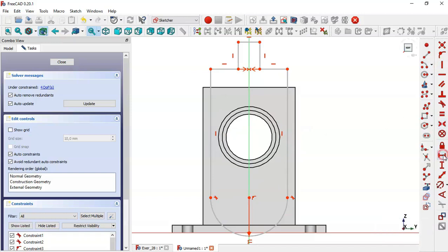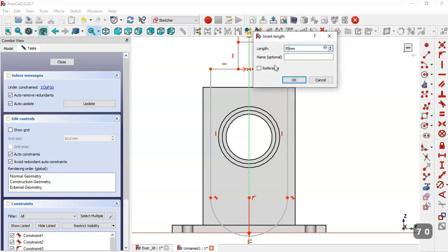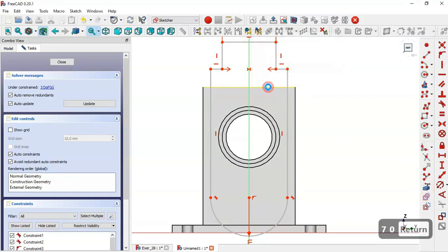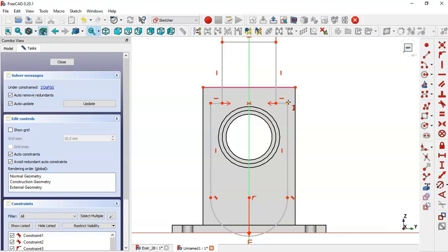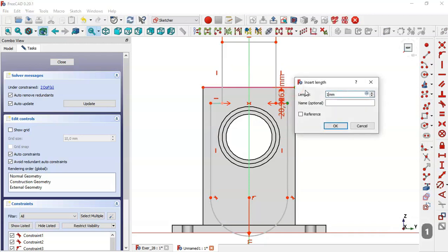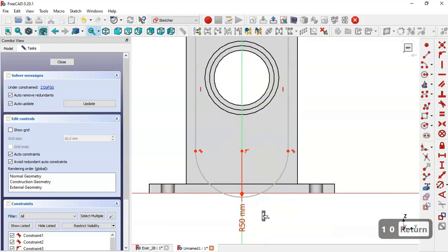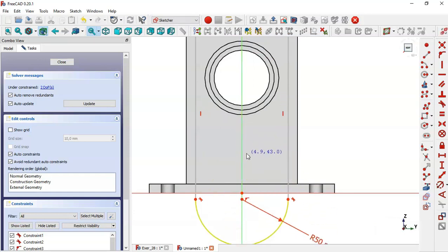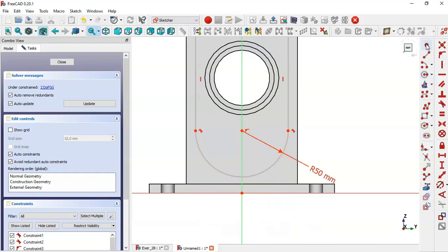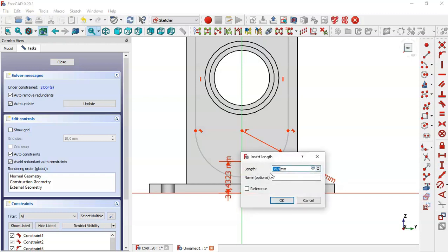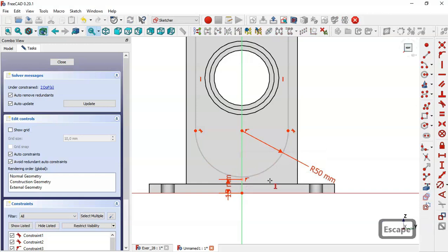And now select this horizontal distance tool, here set 7, and now use this tool to extract this edge. Drag this point, and now select this vertical distance tool, select these 2 points and set this distance to 10 millimeters. Okay, now we select this tool here and we create a point in this line here, and we select this vertical distance tool, we select these 2 points, and the distance here we set 15. Okay, and now we select this line and this point and we do this.